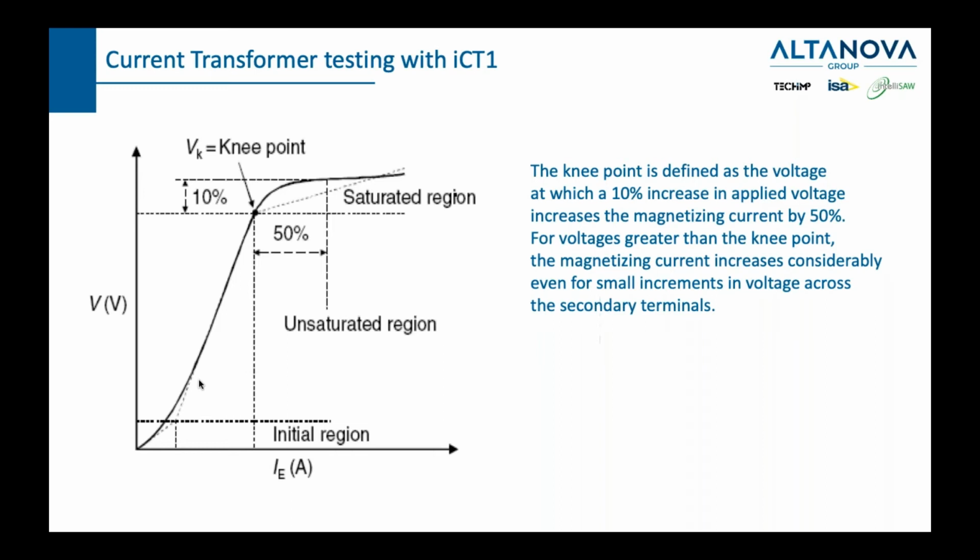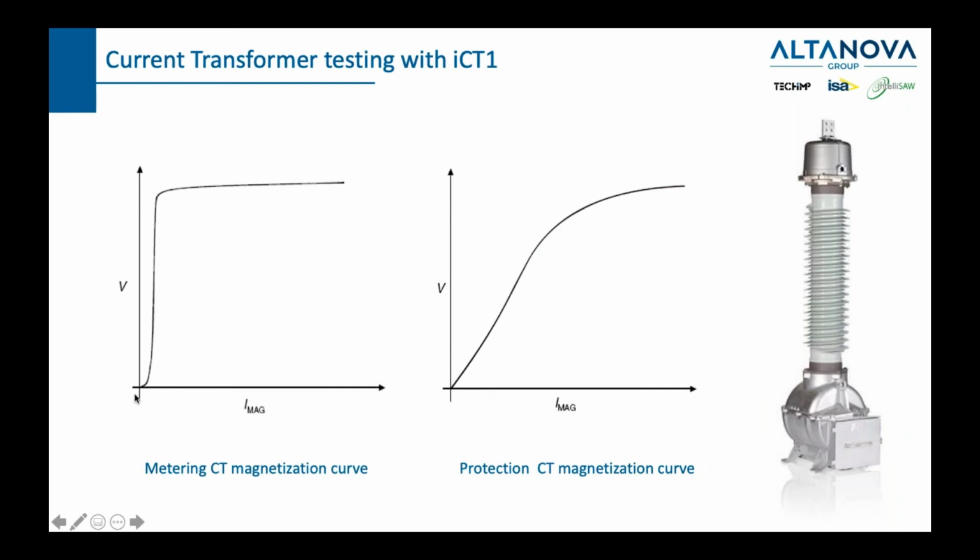You will stay in the same position, you will have the same current, which will then not provide correct information if we talk about protective CTs, and which will then protect the metering devices if we talk about metering CTs. And since we also spoke about sharp magnetization curves, we can see that for a metering CT, you will have something like that as your magnetization curve, while a magnetization curve for a protection CT will look something like this.